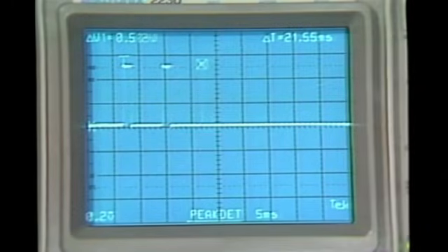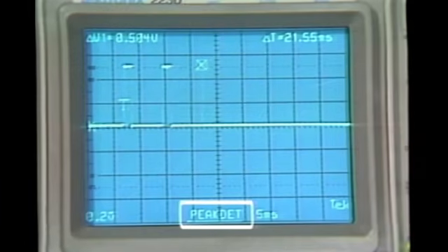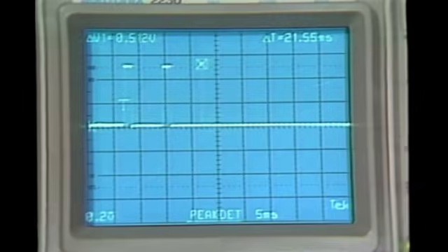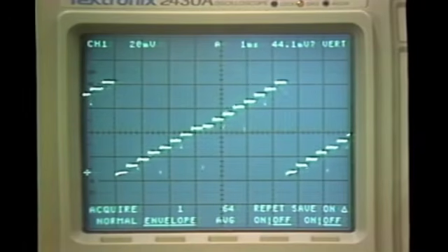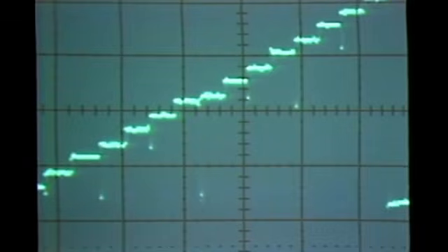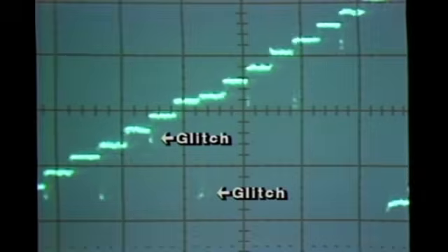In the Tektronix 2230, the peak detect mode avoids missing signal details by always sampling at 10 megasamples per second. This means the 2230 can capture signal details as narrow as 100 nanoseconds. The Tek 2430A uses a different approach to capturing narrow signal detail. The 2430A uses an analog peak detection circuit prior to the A to D converter. This circuit continuously follows the signals between samples. Then peak values are held long enough to be sampled during the next A to D cycle. Using this technique, the 2430A can trap glitches as narrow as 2 nanoseconds and hold them for sampling.